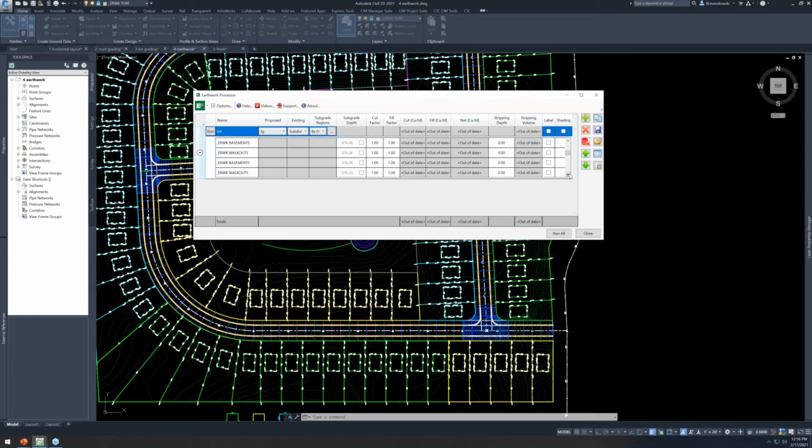And doesn't look like any of them are right. So it reads the elevation from the polyline. Now, if that's not correct, what we can do is override it right here. So say those were supposed to be 1.5, lookouts were to be, okay? Now you can set this ahead of time, or you can just simply put them in right here.